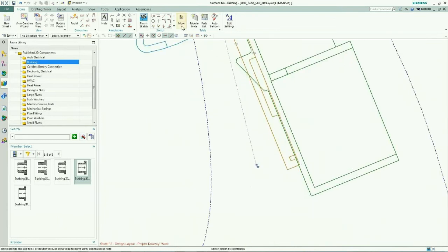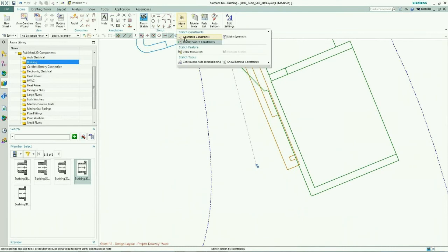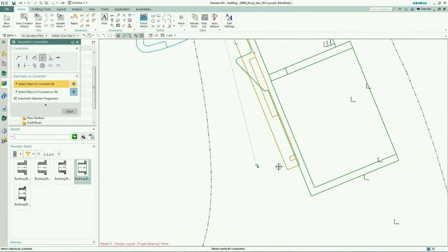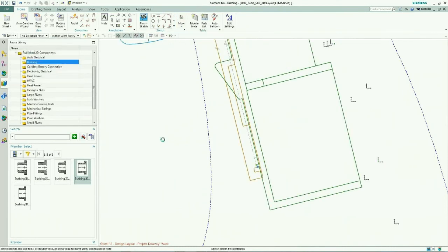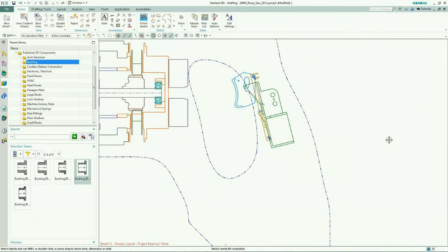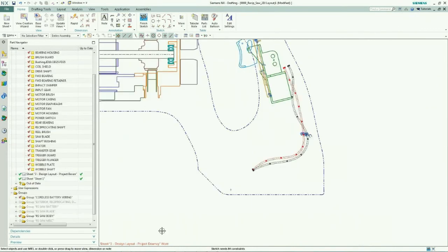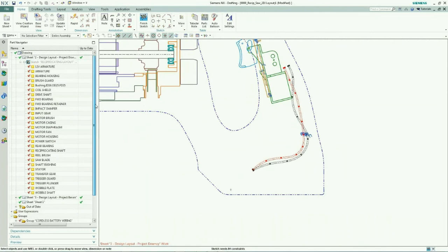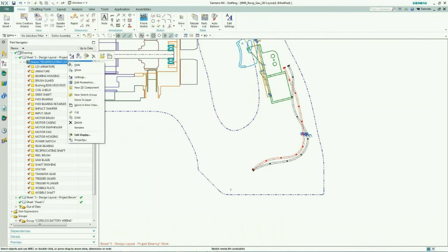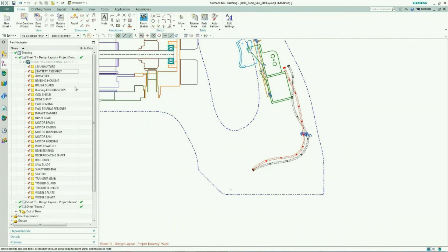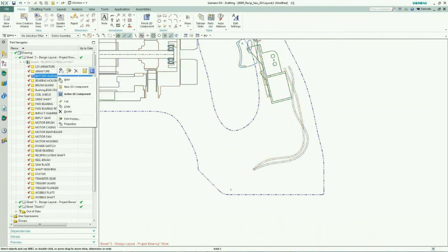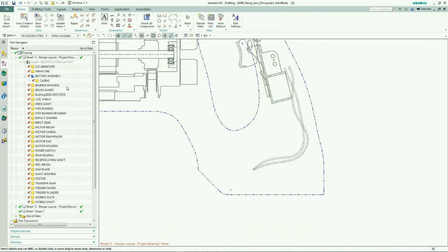and get it ergonomically suitable. Once we're editing these geometries, we can match it, add in more geometries, conform to other patterns, other existing geometries, and you can see also it's not limited to just mechanical applications. We can add in representation for our wiring, and because it's 2D, you don't have that ridiculous behavior of splines in a 3D world trying to represent a thin wall of a wire.